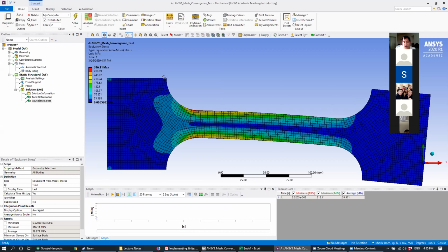But just for educational purposes, and so you have more control over how much you step on it, usually it's not bad to do it manually, especially with simulations that take at most maybe 10-15 seconds to run. But if you are running a simulation where it takes maybe an hour or two to run, then automating it would be smart. So you don't have to sit at your computer for 5 hours just to run the test. You can basically run it overnight. So I'm pretty sure ANSYS does have that capability to automate a mesh convergence test. I've just personally never used it myself. Thank you.